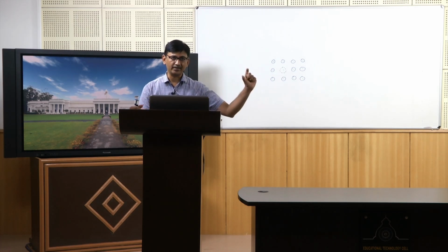The meaning of thermodynamic defect is that you can find the quantity of this defect in a particular material only by knowing the temperature, and it is dictated only by the temperature. So, I cannot increase or decrease the number of vacancies in the material. It will be dictated only by the temperature my material is at that particular point.